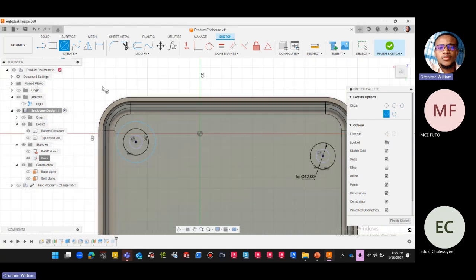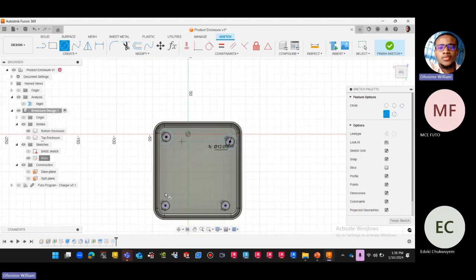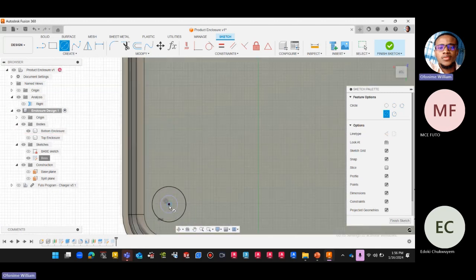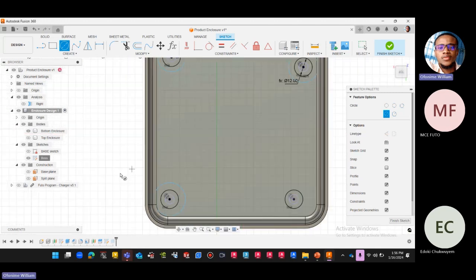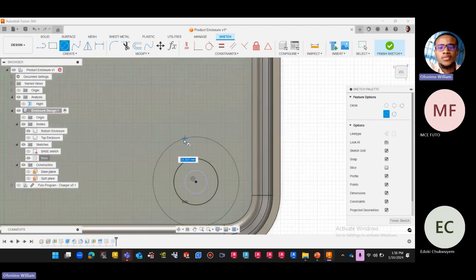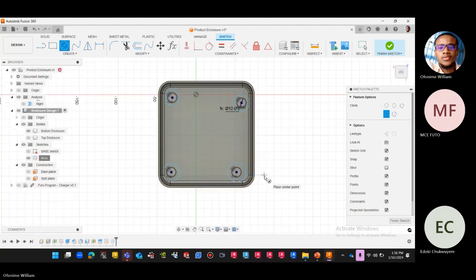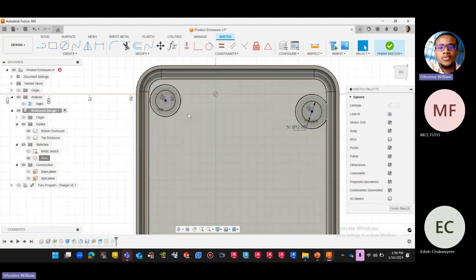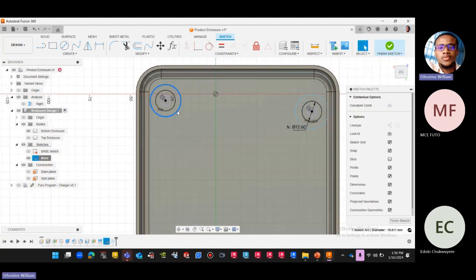It's a circle. I just picked a circle. Make sure they are on the same point. Just pick and drop, pick and drop. That's what I mean by that. Click on the center so it snaps before you pull your hand away. Snap the middle, pull out, right? Now you could assign the dimension to this,